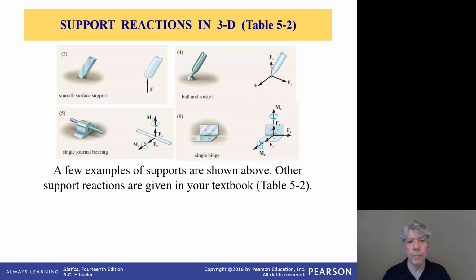It's not too bad. The hinge, you'll notice, has almost all of the supports. It's almost like a fixed connection between two parts. The only kind of load that it does not transmit is a moment about the y-axis. Of course, the reason for that is that a hinge is designed to pivot on the y-axis. You don't want it to resist a moment on the y-axis. You want the hinge to be able to open and close without resistance.